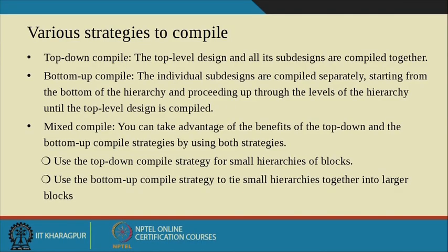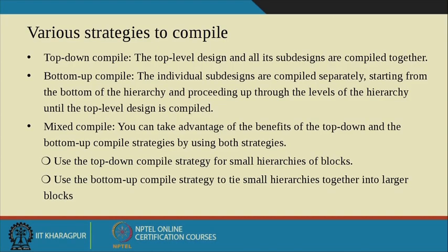Whenever we are compiling, there are various strategies or techniques. One is the top down compile mode, which takes the top level design and compiles all its sub designs together. In the bottom up approach, the individual sub designs are compiled separately, starting from the bottom of the hierarchy and then proceeding up through the levels of hierarchy until the top level design is compiled.